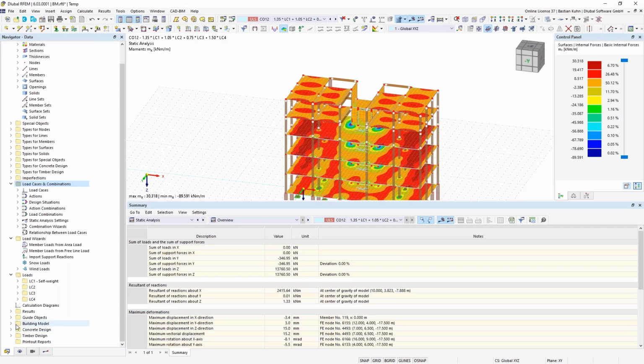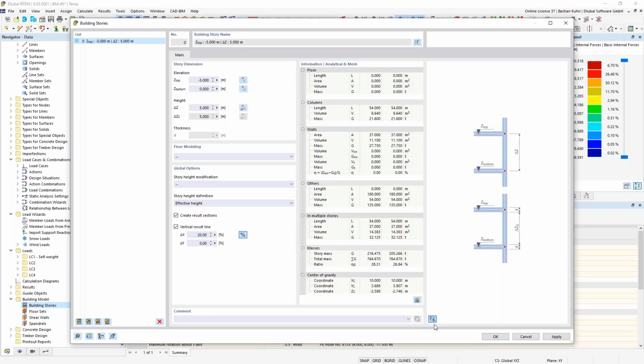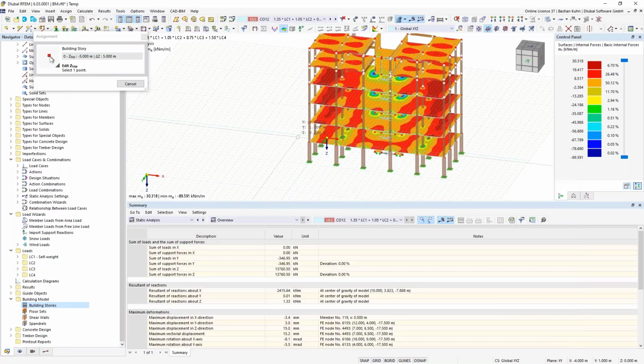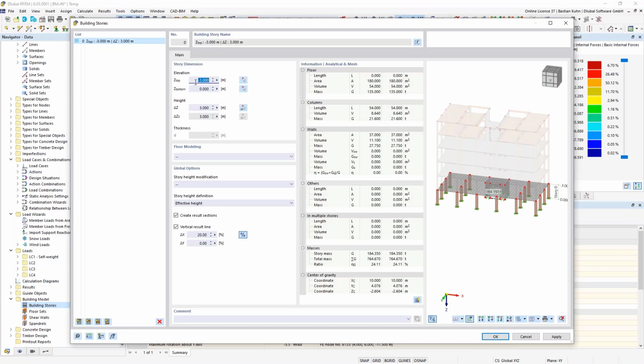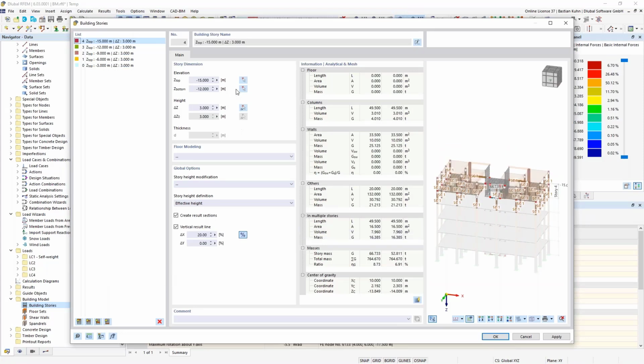Therefore, as we have activated the building model add-on, we will assign building stories. So we go inside in here and define new building stories. There are several ways to generate stories in here, but the usual way probably is to design a building and then assign the stories to it. And that's what I'm showing you here today. The other ways are all described in the manual. Okay, first elevation is -3 meters. And now we can more or less automatically arrange all the other stories.